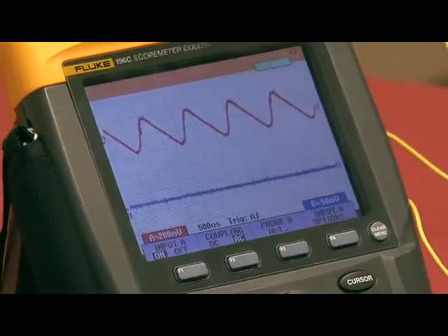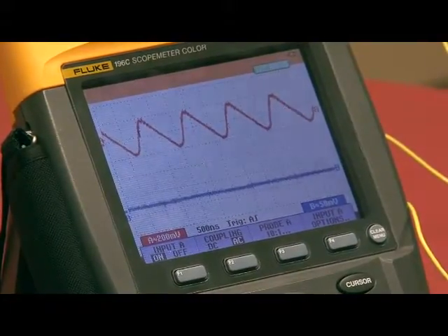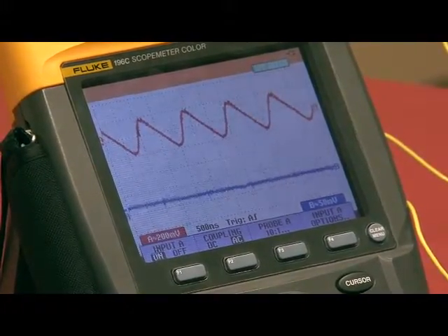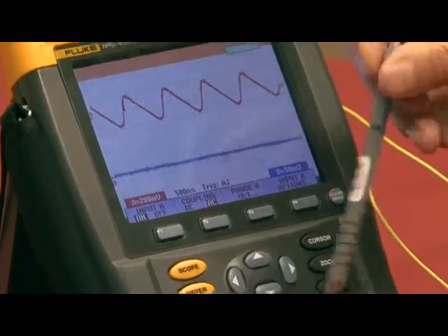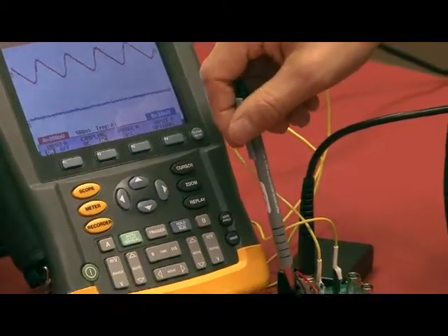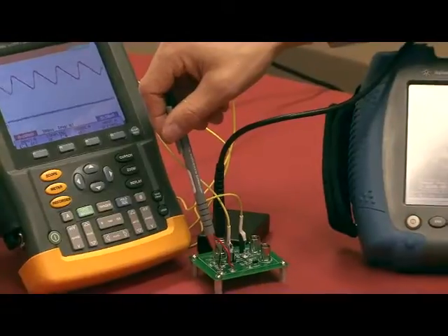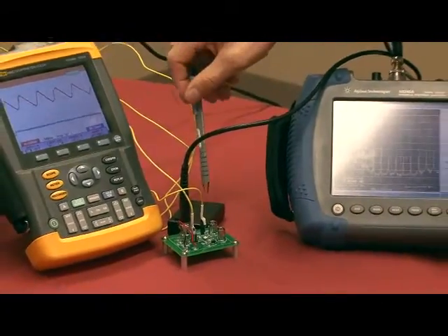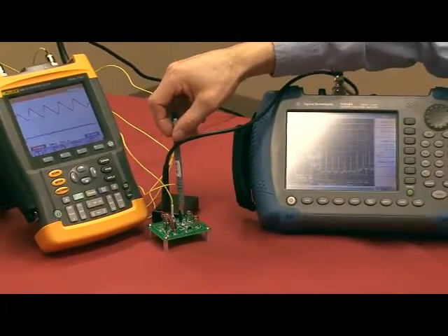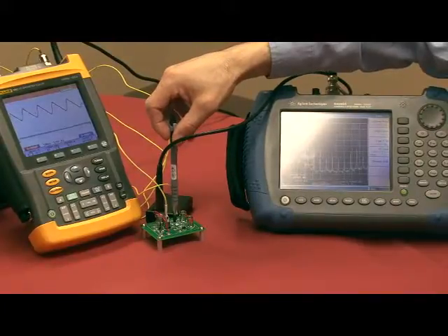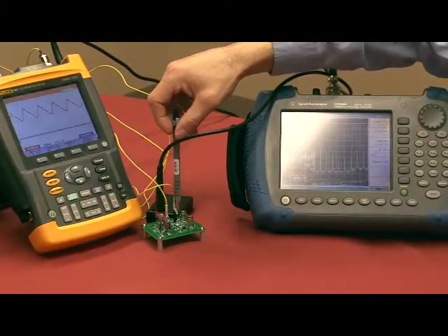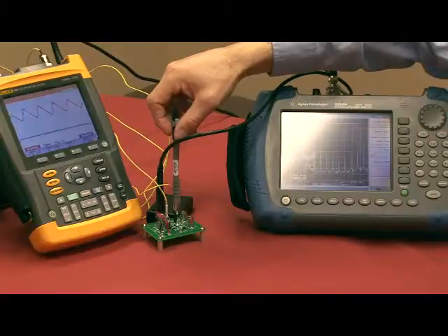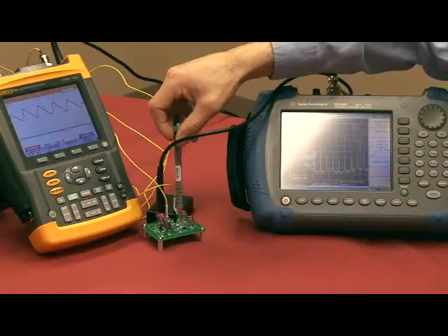There's really three chips of interest. This one here is the DC-DC converter, and over here we have two ripple blockers. On the top we've got a ripple blocker which is configured as a voltage follower. That acts like a power filter, and below it we have the other version of the ripple blocker family, which is a high performance LDO.